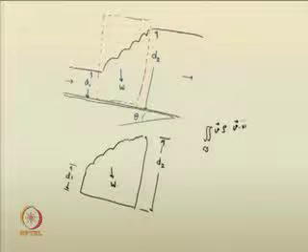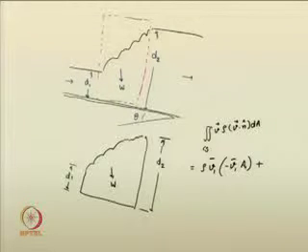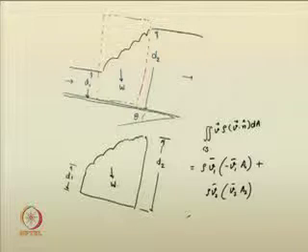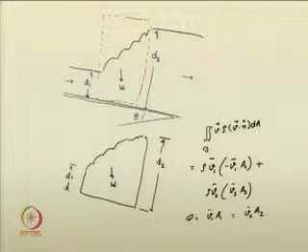V rho V dot n dA, this was nothing but equal to rho into V1 bar, okay, I can just show it exactly, minus V1 bar A1, then plus rho V2 bar A2. So, bar means the average velocity of that section is being taken. This you are quite clear. So, as the conditions are steady, we suggested V1 bar A1 is equal to V2 bar A2. So, you can directly substitute these quantities also if you require.